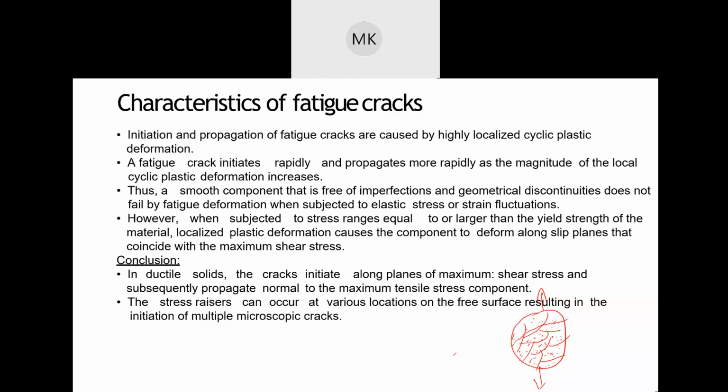So there are two things that happen. One, a surface crack is generated, which is going to create your major crack in the material. And second, all these voids and small cracks that are generated within the material are going to join together in the direction of a dislocation or shear plane, and that's going to be the plane at which your crack is going to propagate and reach failure.